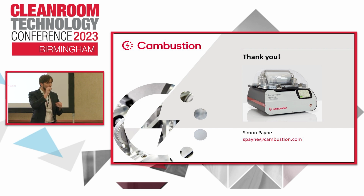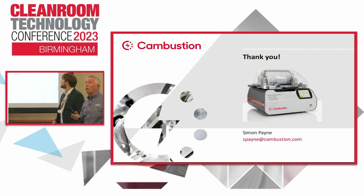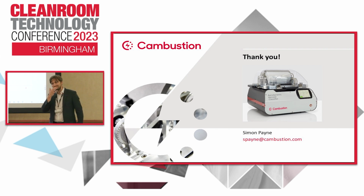Okay. I just highlighted various points where it was clear, due to the particular size cut you're taking, where the multiply charged particles matter. And so to us in a clean room, we are still buying H13 filters or H14 grade filters. You're not trying to change people's minds. It sounds to me like H13 may be more efficient. It's actually very critical. Artificially discounting some of the particles that are there, H13 may actually be more efficient in this technique than we're currently claiming.